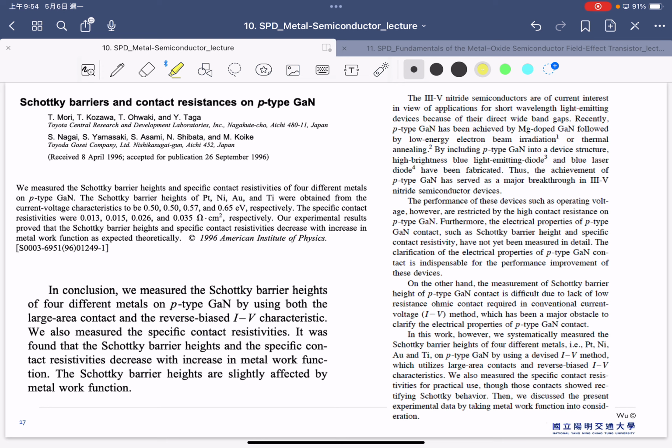Of course, in the silicon world this is not the issue, but right now it is the issue for the other semiconductor materials, like the III-V, like the compound, like the 2D materials. We're always suffering to have a good Schottky or ohmic contact between these kinds of materials.